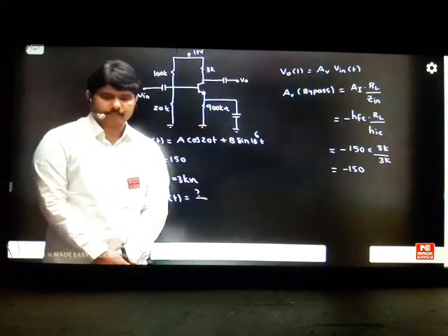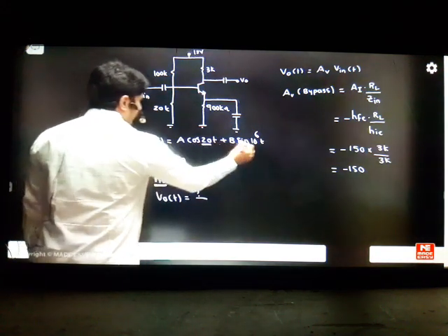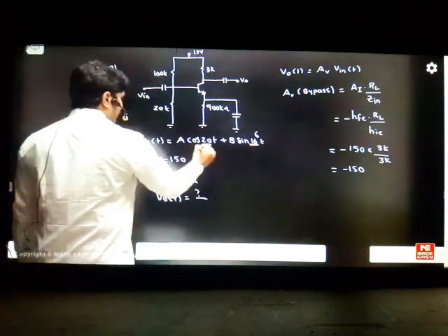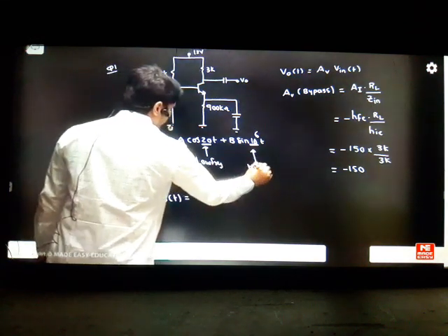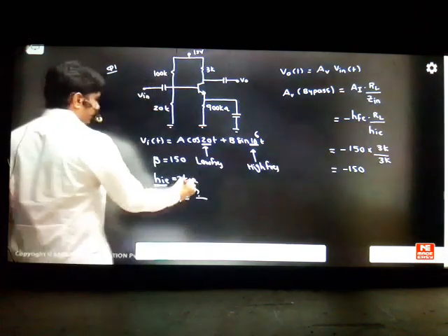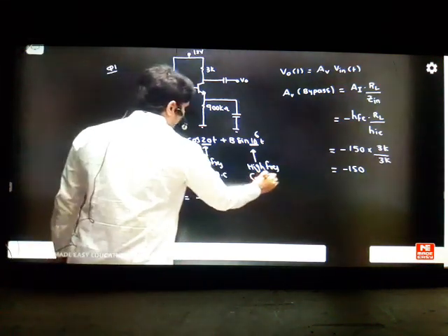The gain is completed. Have you observed why I should give it like this? Is there any logic for this? One is 20, one is 10 power 6. What is the meaning of this? One is considered a low frequency, the other a high frequency. I said in my class one technique for you: coupling capacitor will get open circuit for low frequency, and short circuit for high frequency.